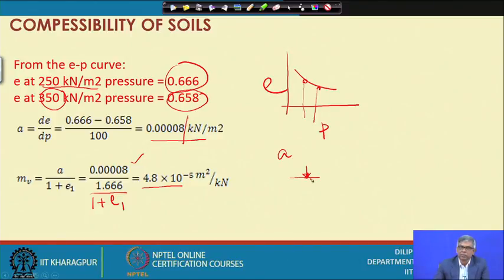When the compression continues and you see there is no change of thickness, that means compression is complete under this loading, and consolidation is completed. Like that, for the second level of loading, the third level, for each level of loading you have to see till there is no change of thickness. So, at the end point for each pressure we get the thickness.